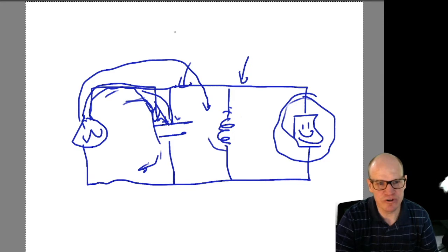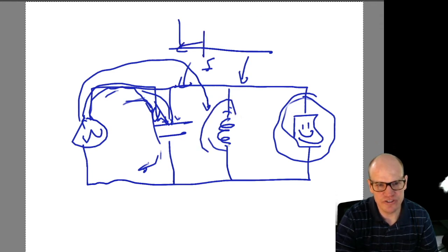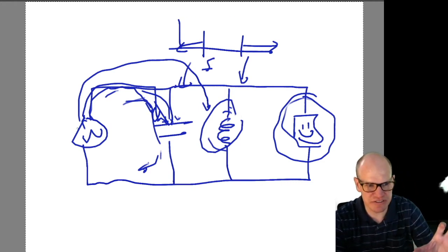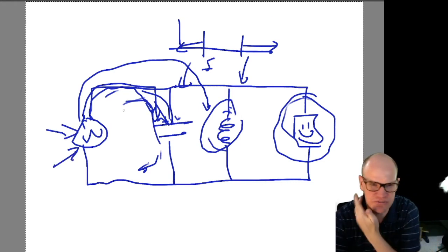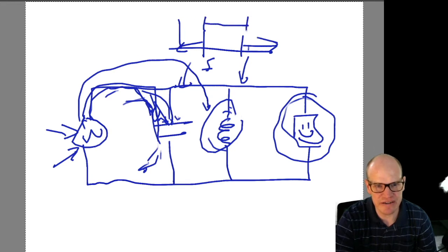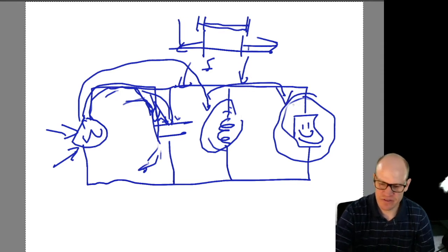And so you have a window where it's like, here's my frequency response, and all the current that's down here will flow through the inductor. All the current that's up here, like any frequency that comes into my system right here, will be filtered out by the capacitor up here. So it will all pass through the capacitor up there, which gives me some narrow band where it will go through my resistor.